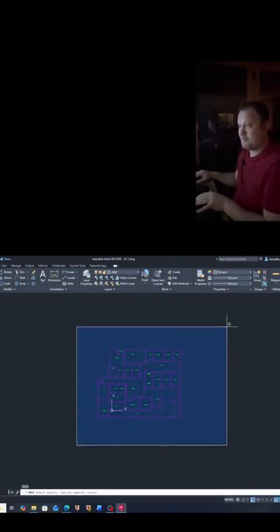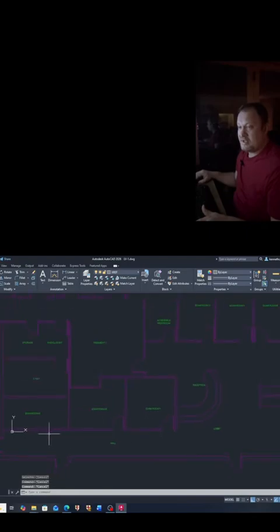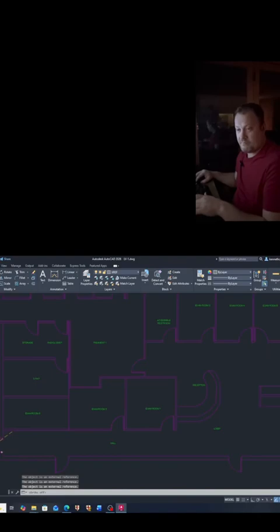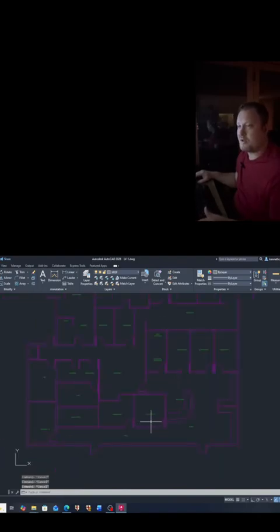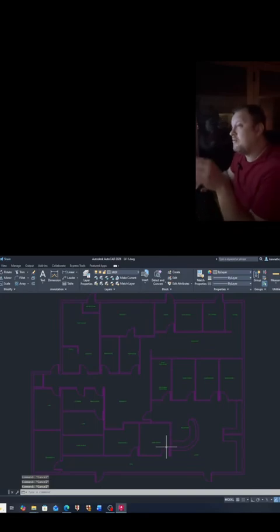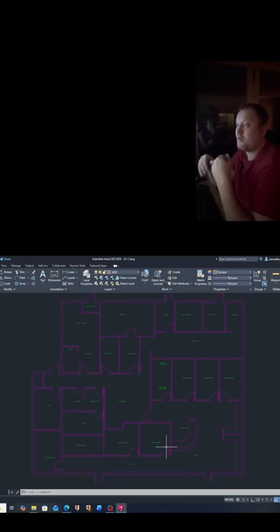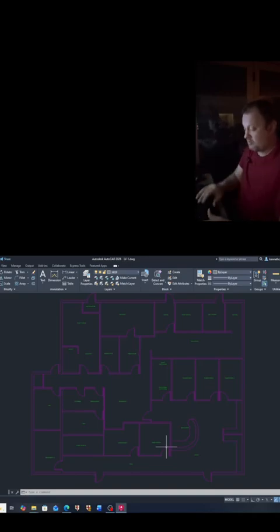So bear with me here. I don't want my UCS showing up right here. I'm just going to move it. Okay. So when I'm working in this, for one, we want our colors to print properly. And again, we can go into the CTB file later, but at the company I worked at previously, number 8 would print lighter so that when all the work you did would show up more bold. It would print boldly, so your work stood out.